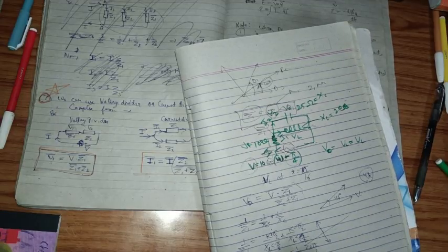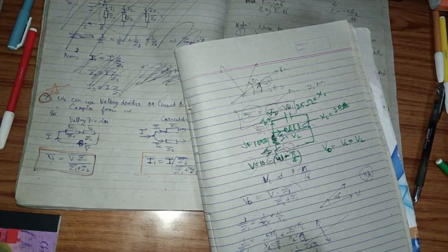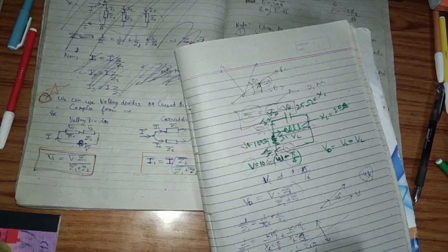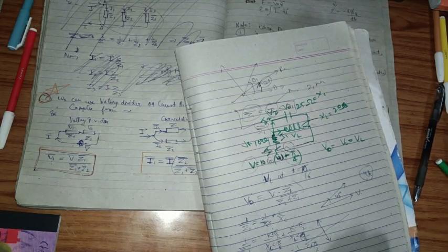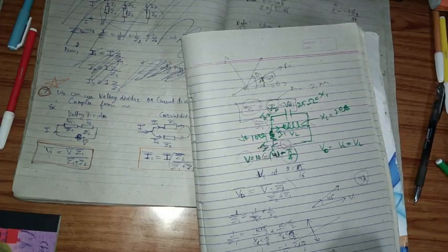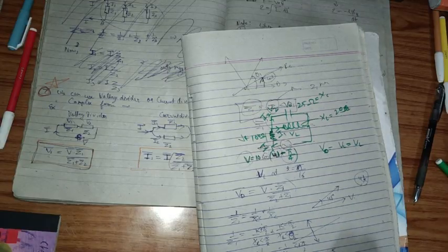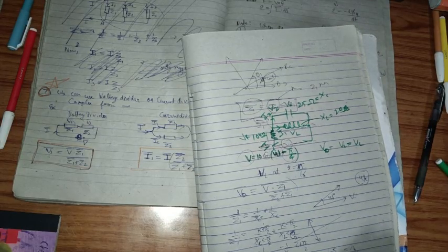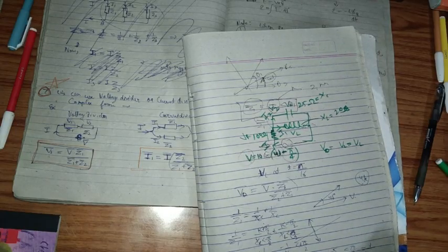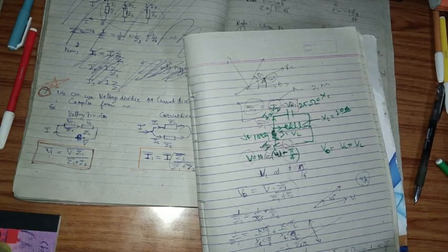that gives me minus pi by 25 into 20 at this pi by 2 angle, that is actually equal to 1 upon 100 at minus pi by 2 angle with this reference. So from the reference I can say that this z1 vector is actually the reciprocal of this, given by this plus pi by 2. So the z1 is found out, and now I have to take the sum of this z1 and z2 vector.